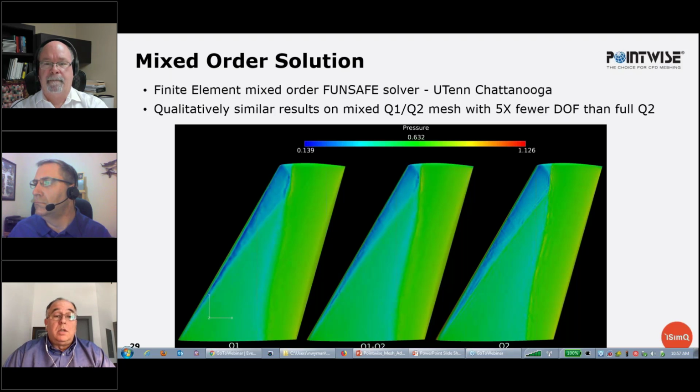We're using Lagrangian, and we know that they have a ringing issue on orders higher than 3 or 4. We believe the mesh order above cubic is probably not necessary, as the geometry is rarely higher than cubic. If you have an isoparametric finite element solver, that means the solution space is the same order as the mesh, and they don't tend to go higher than cubic in our experience so far.